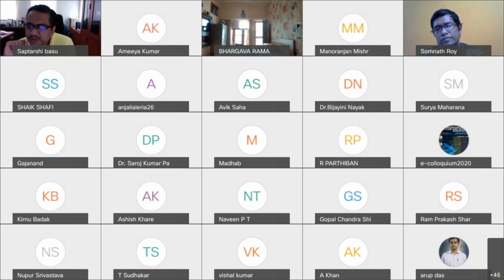But in swirl stabilized flow, because of these hydrodynamic transitions, which are not present in the bluff body, the flow physics is abnormally complicated to begin with. I have not seen a paper which gives a full-fledged understanding of the swirling flow. For example, people cannot predict the conical breakdown at all. We can hypothesize certain things, we can propose certain mechanisms, but there is no criterion or mathematical basis by which one can say, okay, this is going to happen. So it is after the fact.